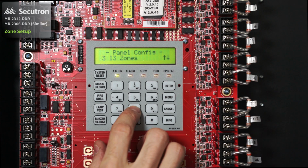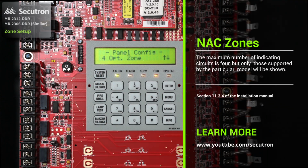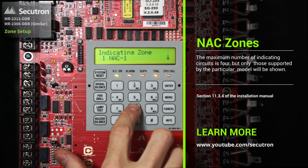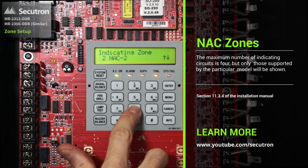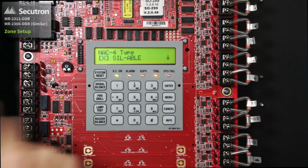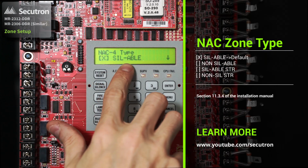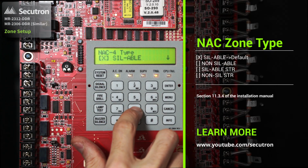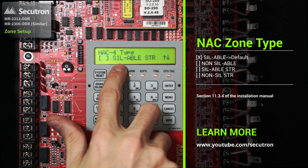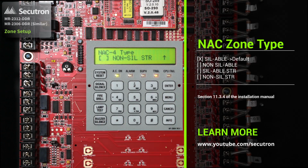The next feature under panel config is our output zones. With our output zones, we config our NAC circuits. So we have our indicating zones NAC 1, 2, 3, and 4. If we select one of these, we can decide what type of NAC circuit it will be. Will it be a silenceable, as selected by default, a non-silenceable, a silenceable strobe, or a non-silenceable strobe?